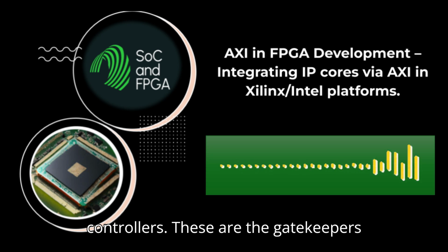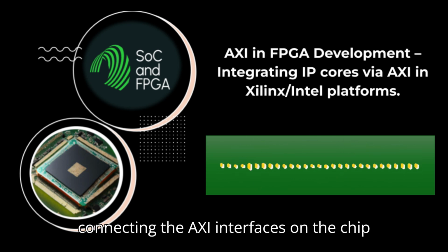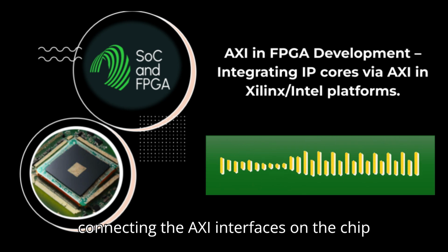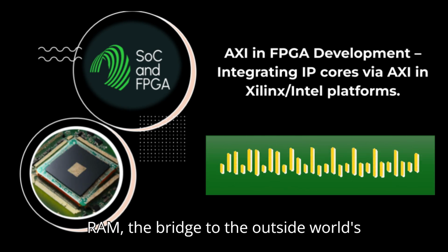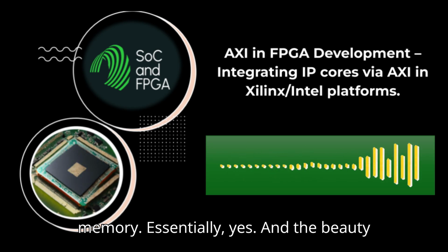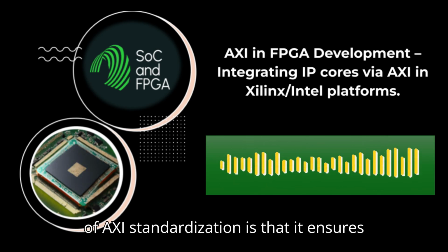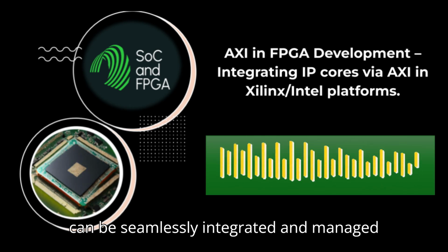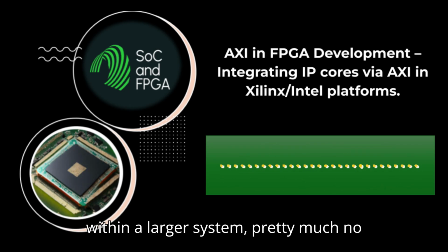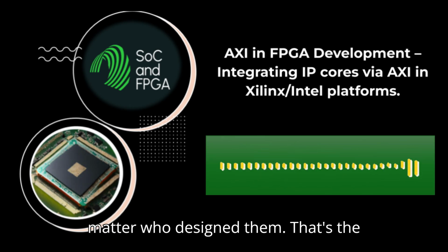Okay. Any others? Then you have memory controllers. These are the gatekeepers connecting the AXI interfaces on the chip to the external memory, like your DDR RAM. The bridge to the outside world's memory. Essentially, yes. And the beauty of AXI standardization is that it ensures these complex, high-performance blocks can be seamlessly integrated and managed within a larger system, pretty much no matter who designed them. That's the power of the standard.